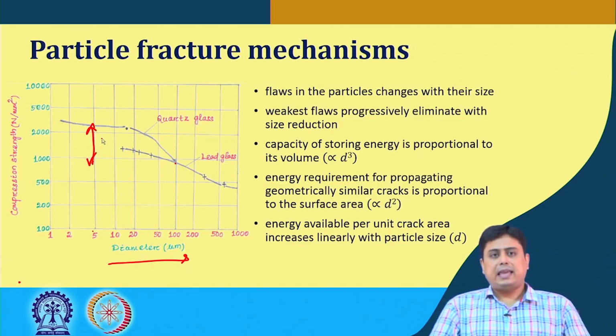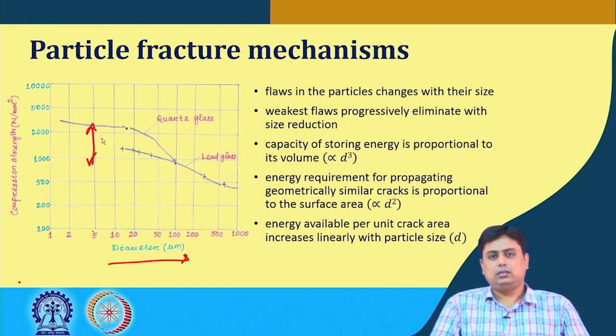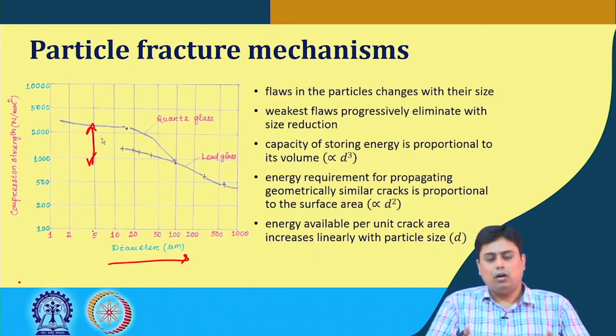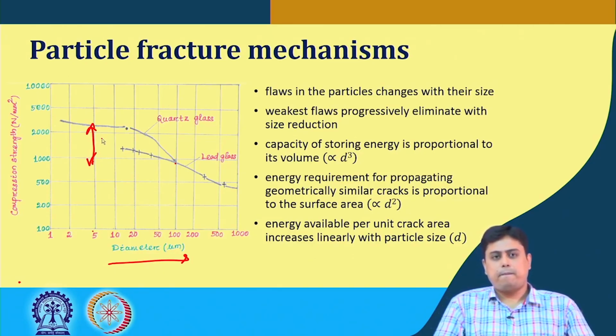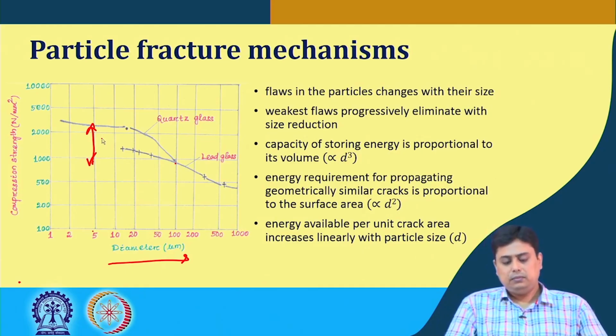It has been seen that the capacity for storing energy in a particle is proportional to its volume. The energy requirement for propagating a geometrically similar crack is proportional to its surface area. As the surface area increases, the energy requirement for propagating several similar cracks also increases, and the energy available per unit crack area increases linearly with particle size.